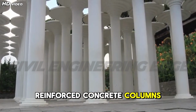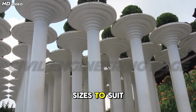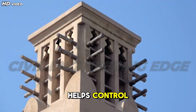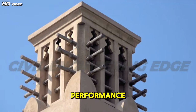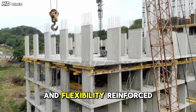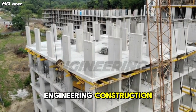Reinforced concrete columns also offer architectural flexibility. They can be molded into various shapes and sizes to suit architectural layouts without compromising structural safety. Additionally, their stiffness helps control deflections and vibrations, improving overall building performance. Due to these advantages, strength, durability, fire resistance, economy, and flexibility, reinforced concrete columns remain the most widely used column type in civil engineering construction.